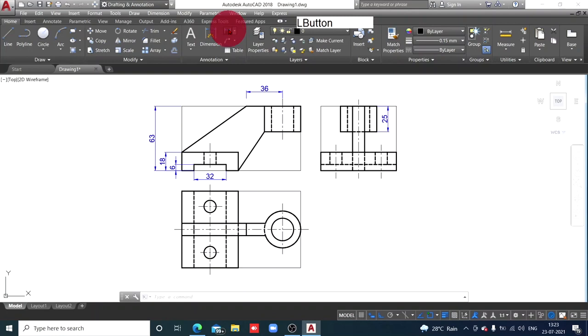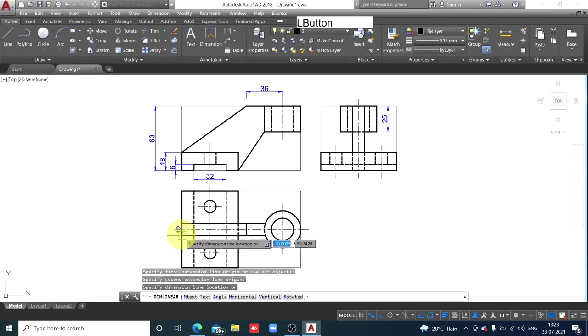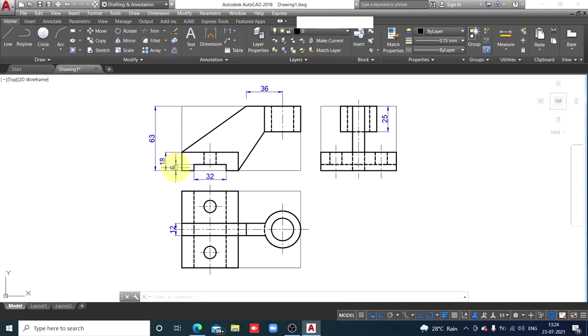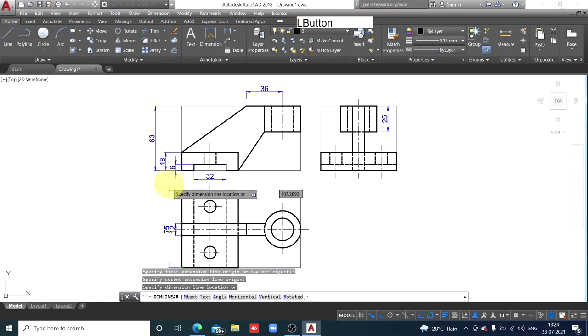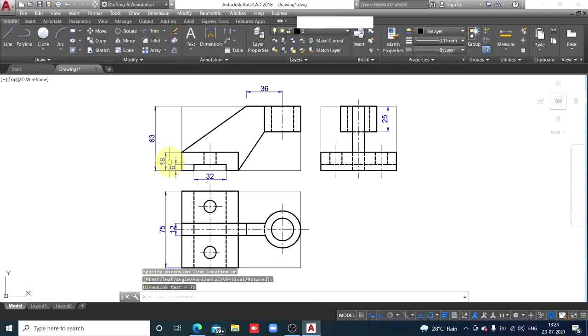Now, it's very easy to insert dimensions. Smaller dimensions first. So, 12 millimeters. And to align it with 6 millimeters, click at that midpoint. So, here dimension will get set up collinear with that 6 millimeters. Check once again what I am saying. Dimension, overall dimensions. Just take cursor at the midpoint of that 18 millimeter dimension. When you have taken cursor at the midpoint, the computer will tell you by showing that triangle there. Click. So, 75 millimeter is aligned with that 18 millimeter.